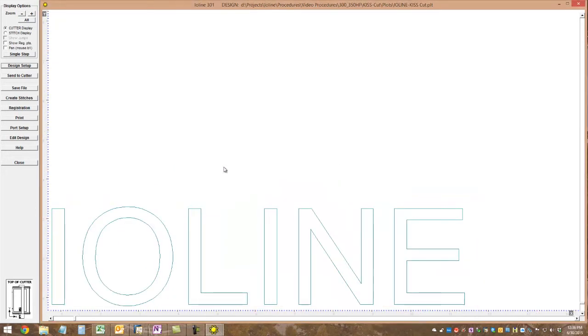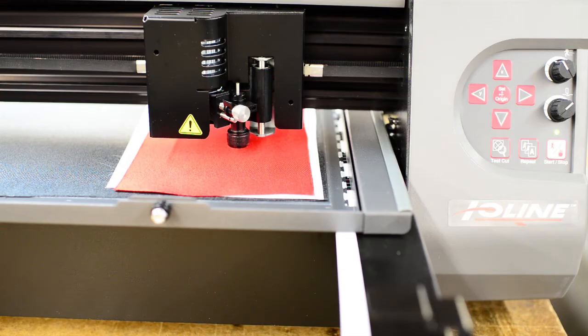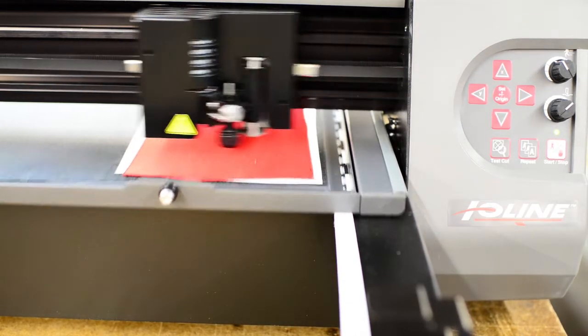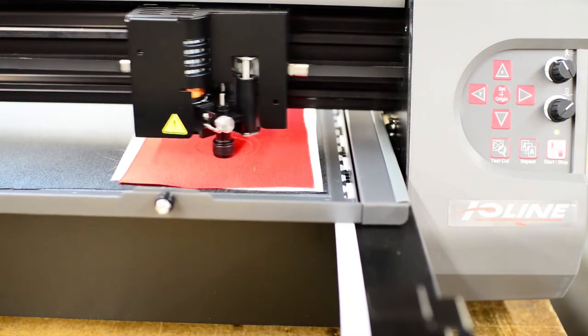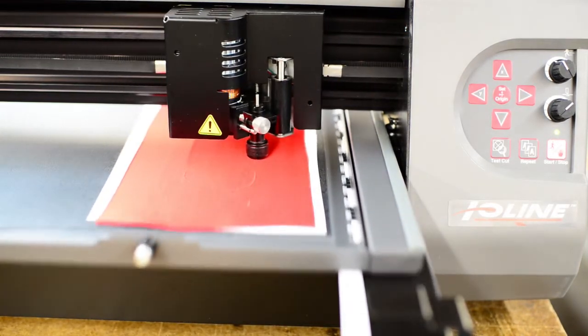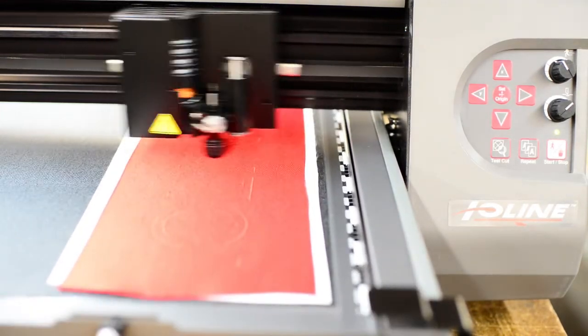And then very simply hit Send to Cutter. And because we had a start point already done on the first layer, each time you hit Start Stop, it will go back to its previous start point and remember where it was in space for every design, for every layer. If you hit Set Origin between those, it ruins the design and you won't be able to get it back.